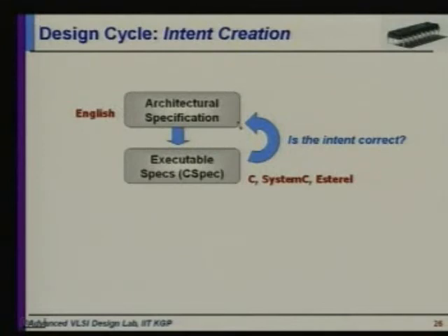What is the instruction set? What are the different addressing modes? How are you going to manage the access of the caches? How do you do resource arbitration between the different blocks which are going to access the cache or access the bus or whatever? So all these things, this planning, is called developing the architecture of the design. And today most of the novel innovations in digital chip design take place at this level, at the architecture level. People come up with new ideas.